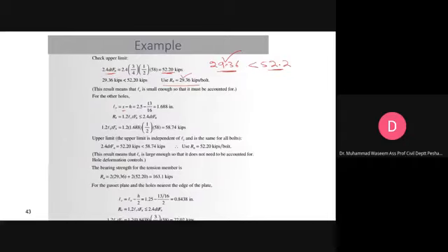We know the center to center spacing S, and we know the hole diameter. Half plus half makes 1, so this is 1.688 inches. Now you have to use the same formulation again. This Lc is different, so you have to check. This comes out to be 58.74 kips per bolt. Now you have to evaluate the upper limit. The upper limit is 52.20. This value is greater than the limit, so it cannot exceed it, and we will stick to the upper limit value.